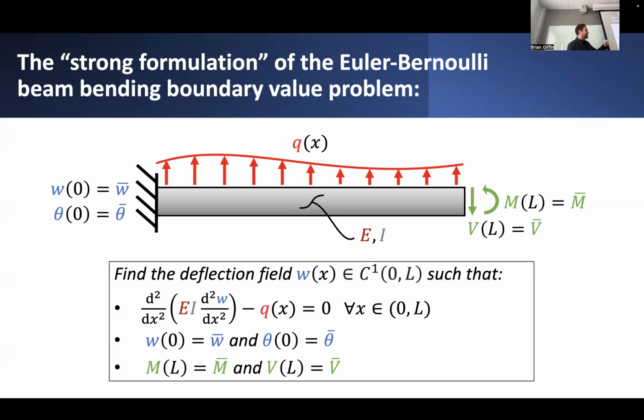Alternatively, we could prescribe the end shear traction, or an end shear load that we might apply to the end of one of these beams, or the end applied moment that we might apply to some end. But if we specify transverse displacement, we cannot also specify this kind of end shear load. Or if we specify rotation, we cannot also specify the moment that would show up as a reaction force to keep the whole thing in equilibrium.